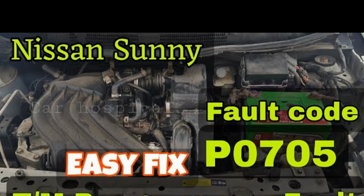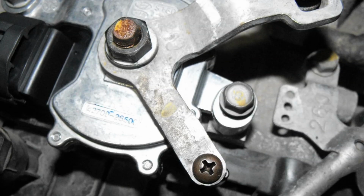If the terminals need cleaning, use an electrical contact cleaner and a plastic bristle brush. Leave to dry and apply electrical grease to the contact areas of the terminals. Using a diagnostic tool, clear the fault codes from the memory and see if error P0705 returns. If the code returns, we will have to test the TR sensor and associated circuits. Turn on the ignition key. Depending on the manufacturer's specifications, the voltmeter should read 12 volts or 5 volts. Shake the connection and see if the reading changes. If the voltage is incorrect, replace the faulty wires or connectors.